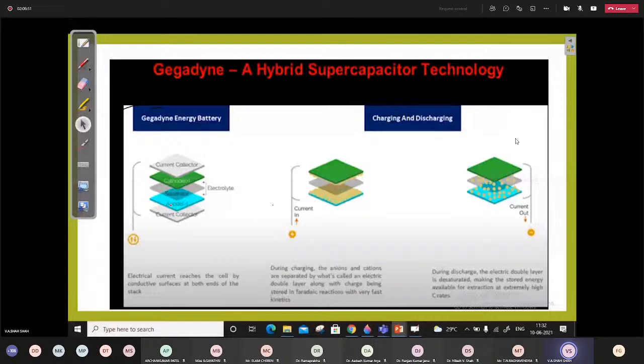Then you have to identify the DC converter and inverter, what type of DC converter you would like to use. So identification of the DC to DC converter and identification of the DC to AC converter, that is related to the motor applications. And then you have to select the appropriate semiconducting switch, and the appropriate semiconducting material for that particular switch.